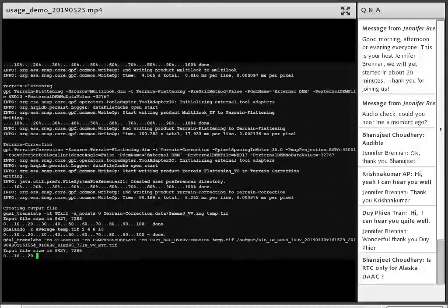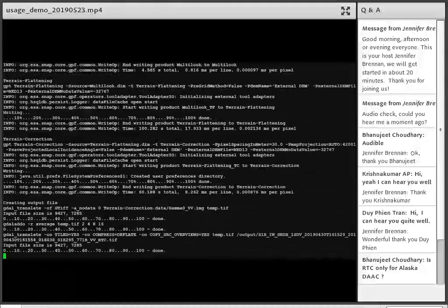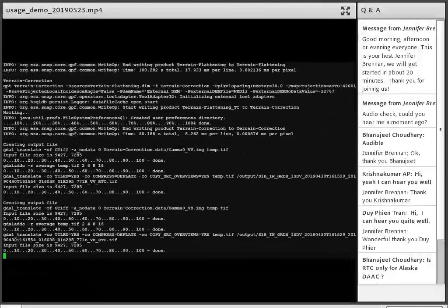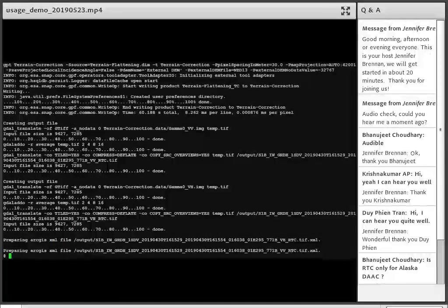Once all the correction has been done, we'll generate our final output products as cloud-optimized geotiffs. Again, this was a dual polarization product. So the original product from the ASF satellite facility contained 2 geotiffs, and for the RTC corrected product, we output a corresponding corrected TIFF for each of those. As the last step, we provide you with your ArcGIS ISO standard metadata file.